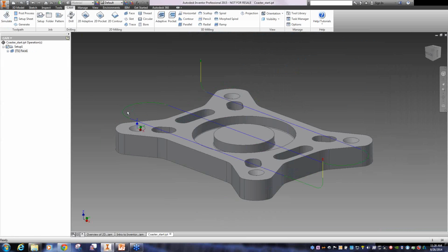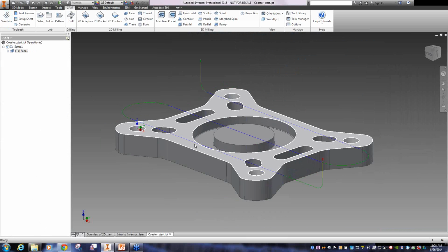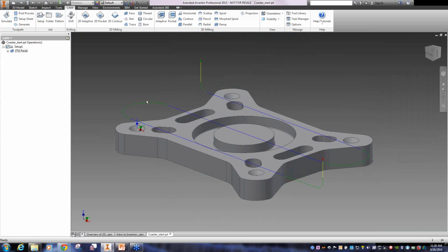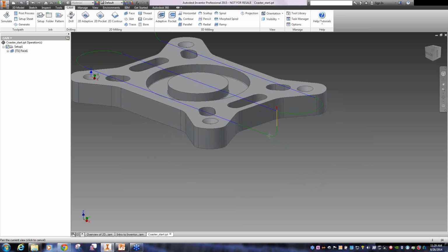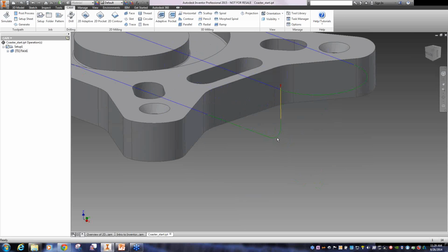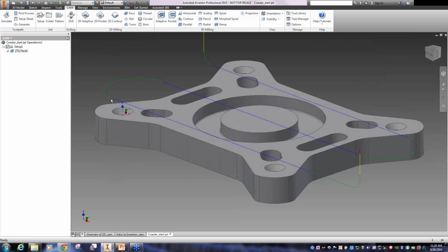Here on the green area it's actually curving to the next path. You can control the speeds and feeds through the cut, linking or transitioning to the next cut. You'll also see here some contouring in from Z, a transition from Z to X, for example. This is all with high-speed machining in mind. Yes, you have the opportunity to do just straight moves, but I wanted to mention that.